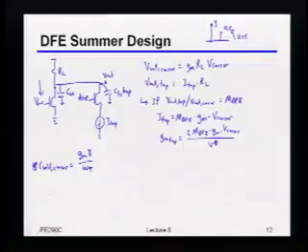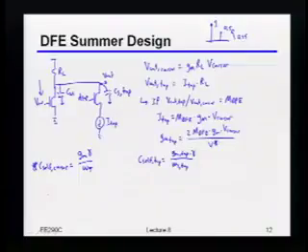And then for the tap, it's going to be something very similar, which is just whatever the GM of the tap is, divided by the omega t of that tap device, times, of course, gamma. I've done things a little bit differently here because you might be using a different V star for that switch device than you are for the input device.